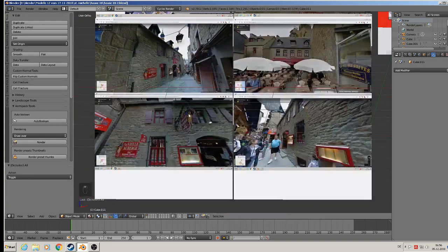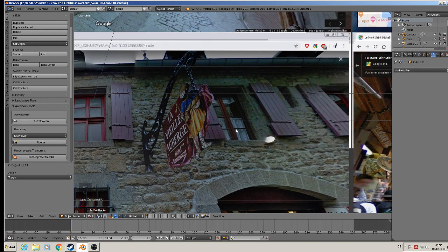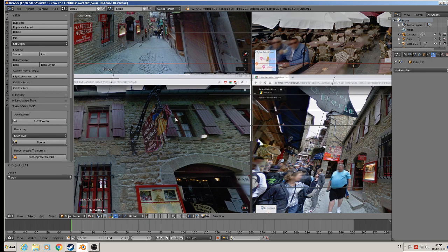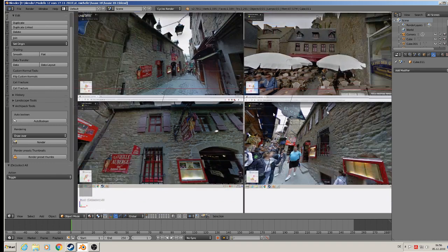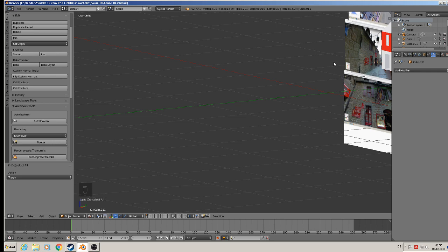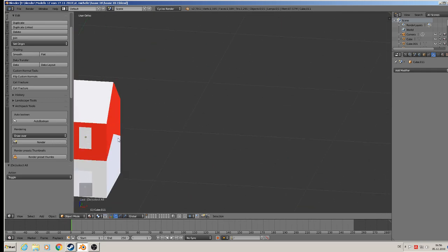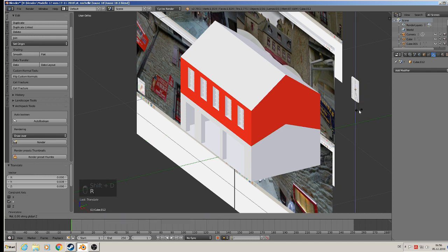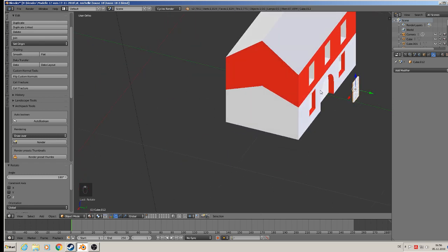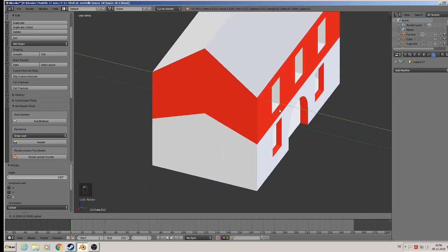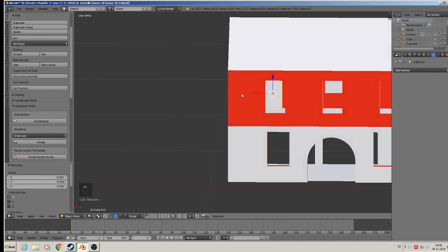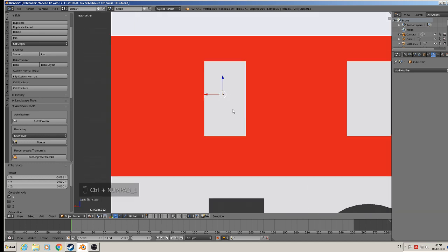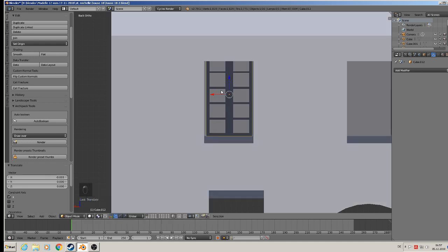So when we look at the front, there we have the same windows, only that is another, but I don't care about. There comes all over the same windows too. So I take the windows from the back side, Shift D, bring them on the other side, rotate Z 180 degrees to rotate them or mirror them. Then I plug them into it, and Control 1 to see it in this mode. Then we get better in solid mode, so we see better what we get there.